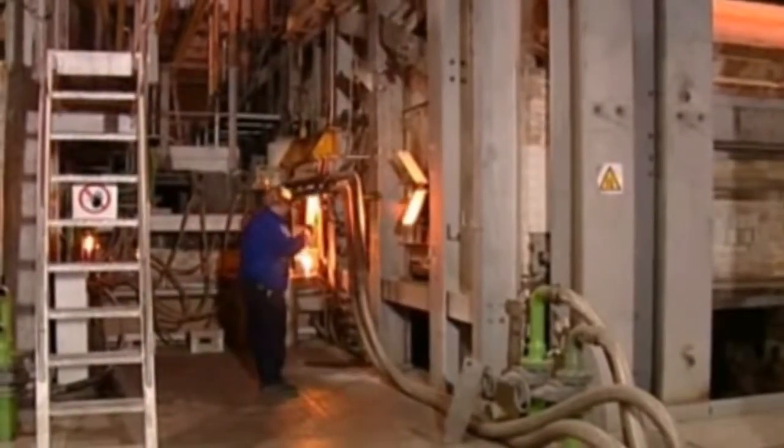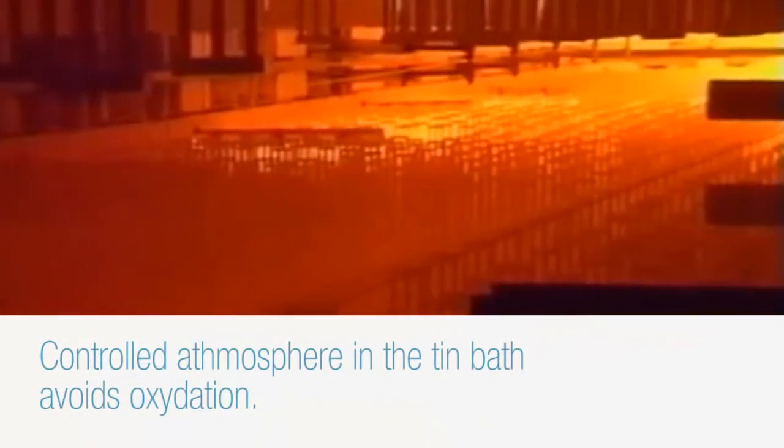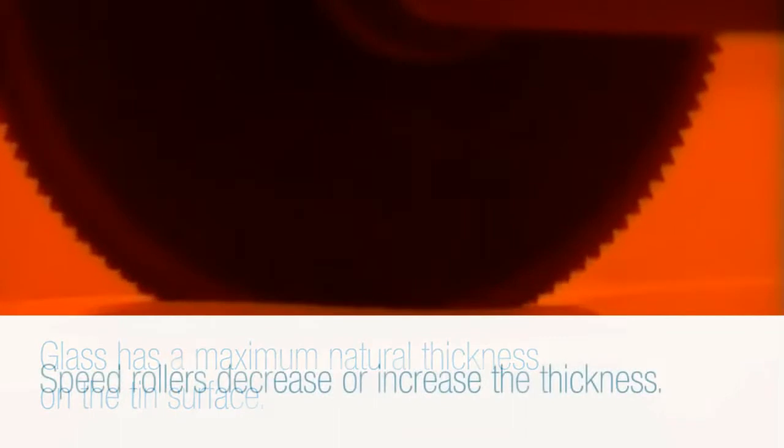Once molten, glass leaves the melting furnace to immediately enter an enclosed bath of molten tin. The molten glass literally floats on top of the tin. Floating along the surface of the tin bath, the molten glass forms a ribbon of perfect flatness. At this early stage of the manufacturing process, the thickness of future glass products is already controlled by way of side rollers and the speed at which the glass ribbon is drawn off from the bath.